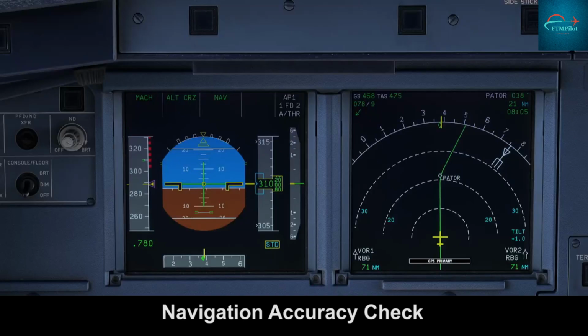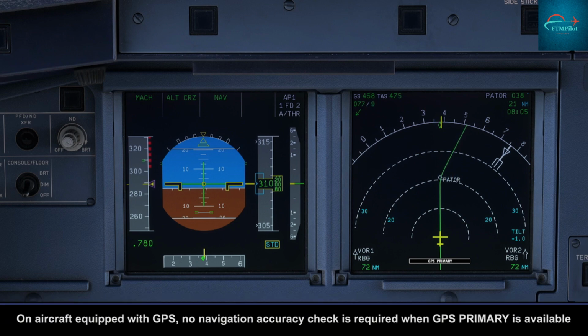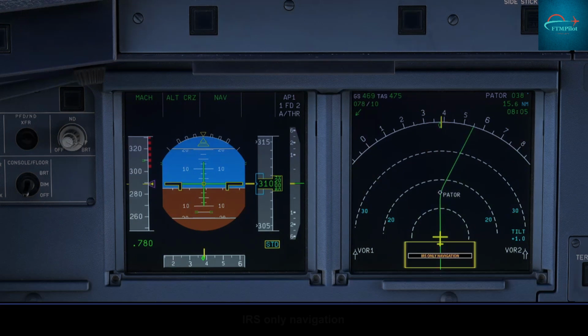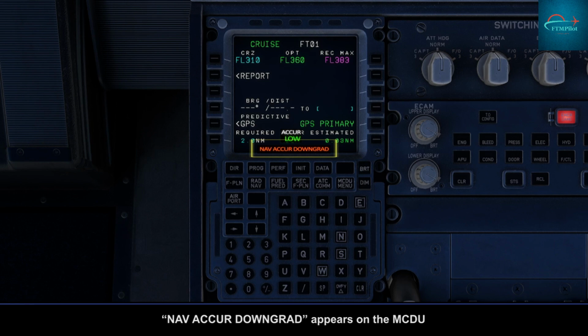Navigation accuracy check. On aircraft equipped with GPS, no navigation accuracy check is required when GPS primary is available. Navigation accuracy must be monitored approximately every 45 minutes when any of the following occurs: IRS-only navigation. The progress page displays low accuracy. Navigation accuracy downgrade appears on the MCDU.